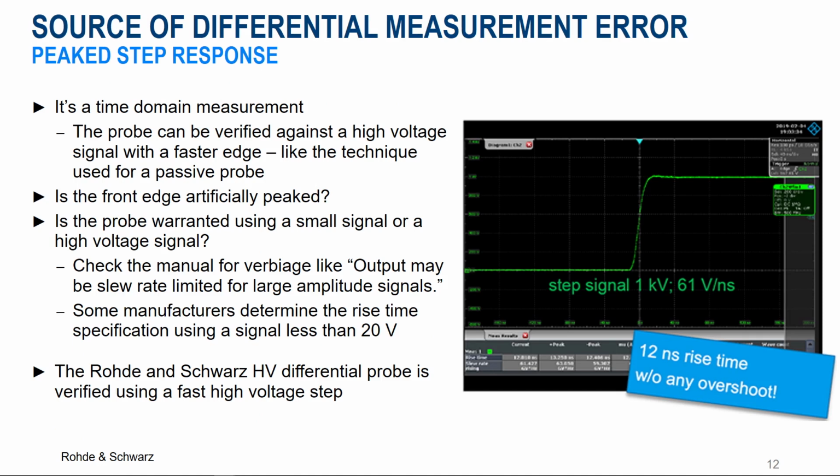When evaluating the rising and falling edges of a gate driver, users should be mindful of a differential probe's rise time specification instead of its bandwidth. After all, it's a time domain measurement, and it's critical to understand how accurately the probe and oscilloscope represent the true signal in the time domain.